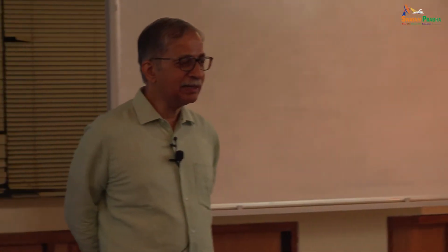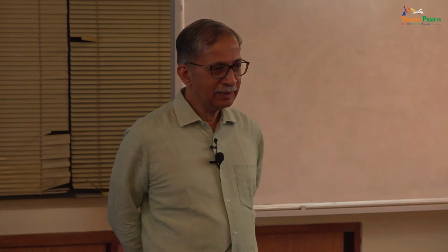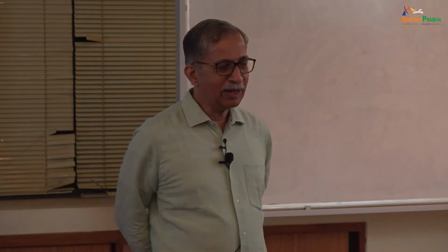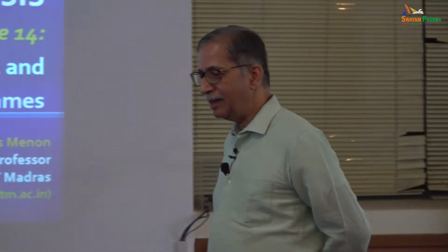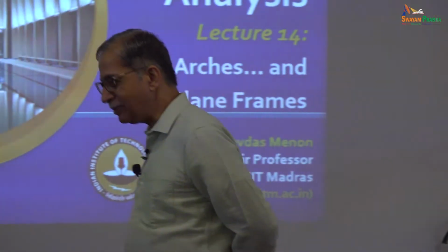What's the additional thing you get in a plane frame? Axial force. Is it compression or tensile? It can be either of the two. What about an arch? Arch is a plane frame member actually, and typically the axial force is compression. Is it clear?